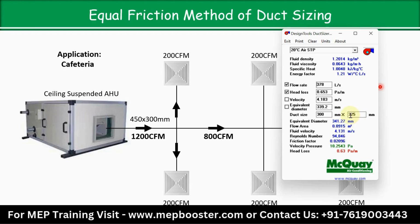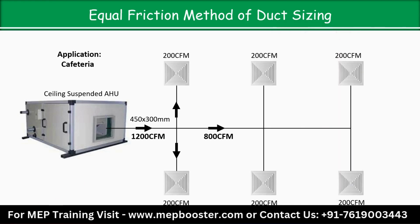Ducts are manufactured in some standard dimensions, as I told you. So 300 height and the width is 350, correct? For 800 CFM the size we have got is 350 by 300. Now when you are supplying 200 CFM to this diffuser, the remaining is 400. So for 400 CFM, how much size?